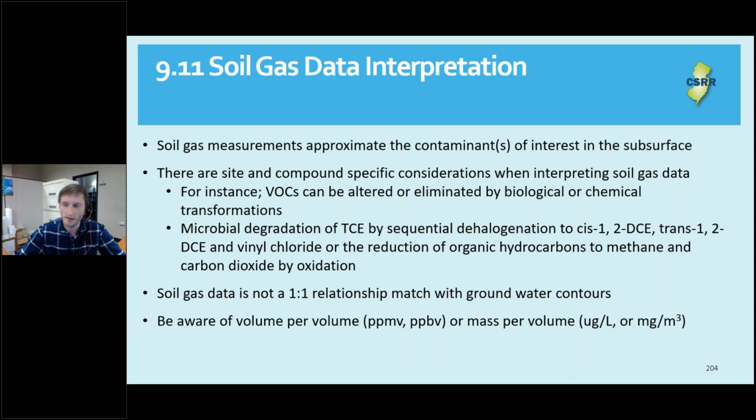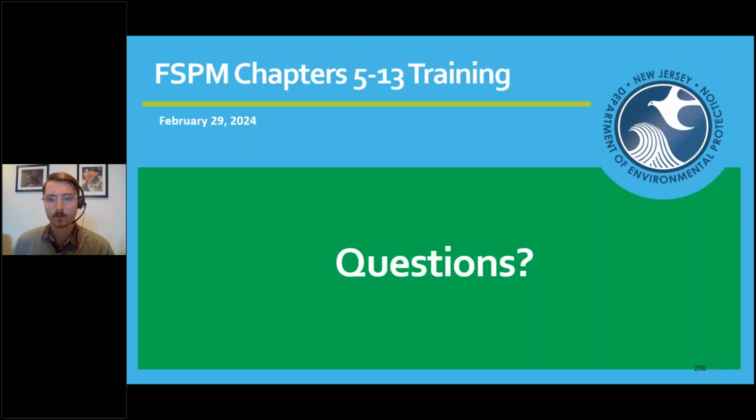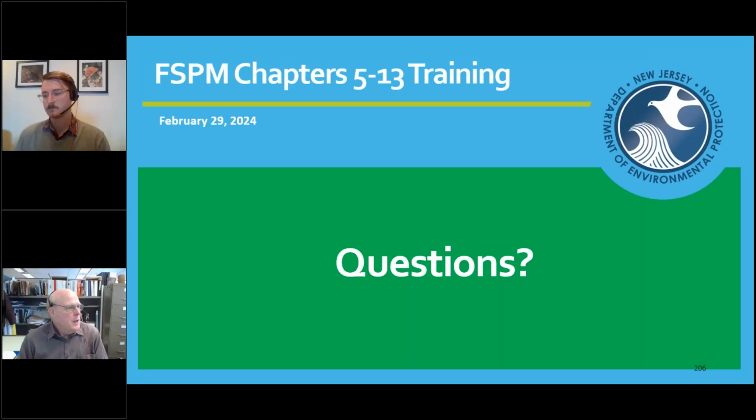Next slide. Okay, thank you very much, Tyler and Carla. We will now begin our first question segment. Our first question came in during Chapter 5. This is an IDW question. Do you need any permits to treat groundwater with an activated carbon on your sites prior to discharge on ground? As far as I know, there is no necessary permit needed to do that. Should be covered by the permit by rule.